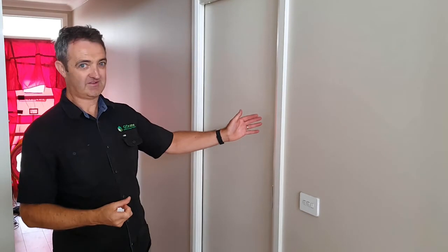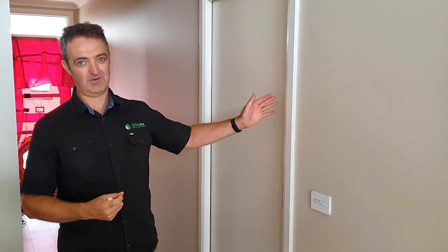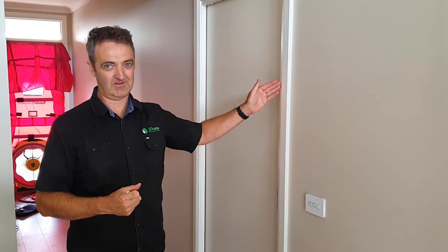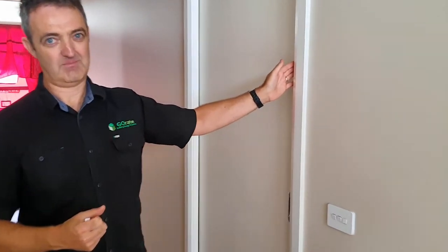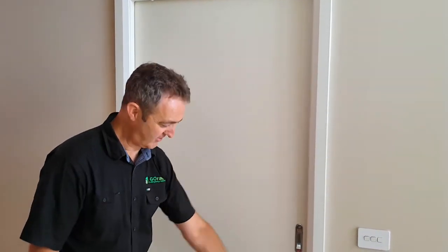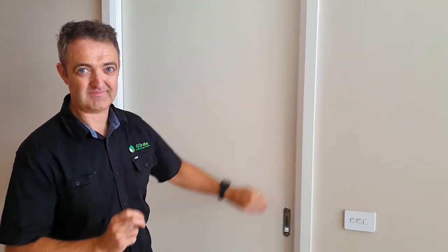And as far as cavity sliding doors go, you cannot seal them. So, never ever put a cavity sliding door between the house and the garage. If we zoom in here, you will just see a massive crack of daylight coming from the garage. So obviously with a massive crack right down the bottom, up the top, down the side, you cannot seal that. So just don't do it.